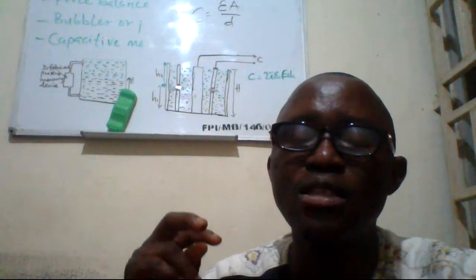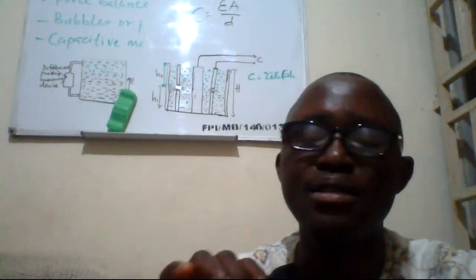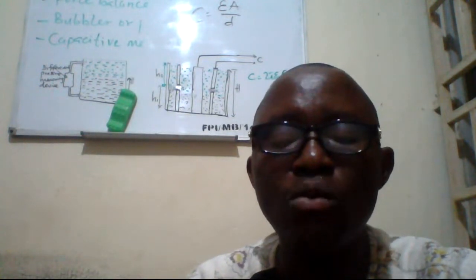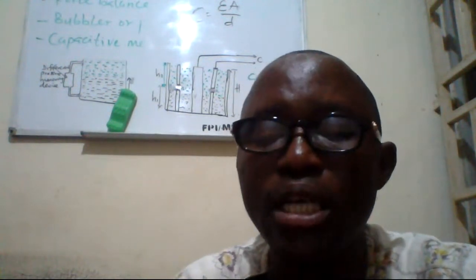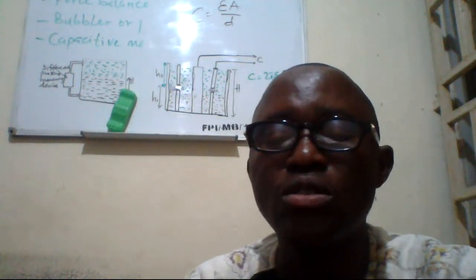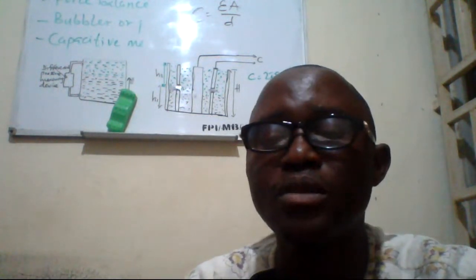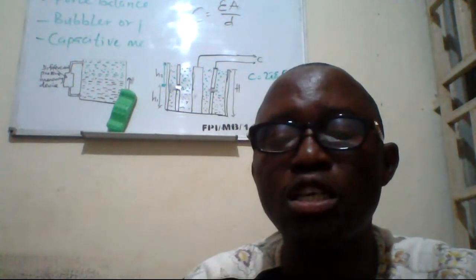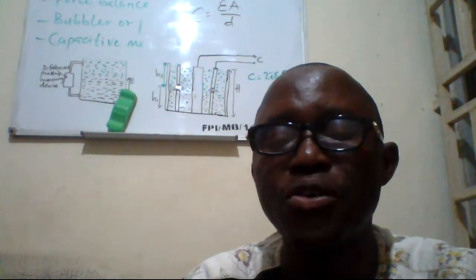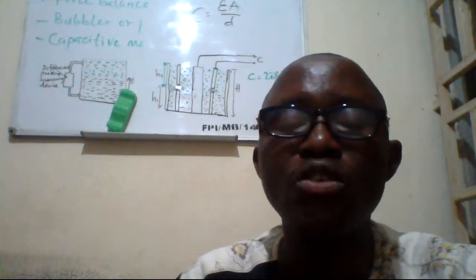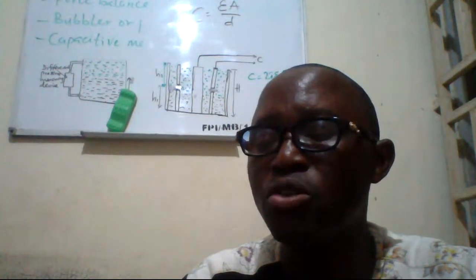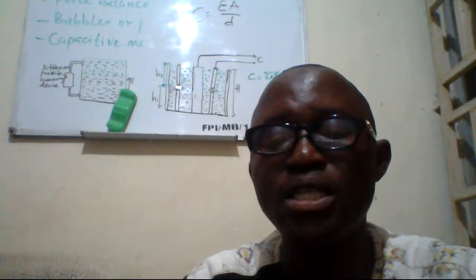When a high frequency electric signal is sent, a capacitance is developed and measured, after which we can use that value to calculate the level of the liquid. The system is very innovative and gives accurate results because it depends on the capacitance developed between the liquid and the vapor. So that is the capacitive method of level measurement.